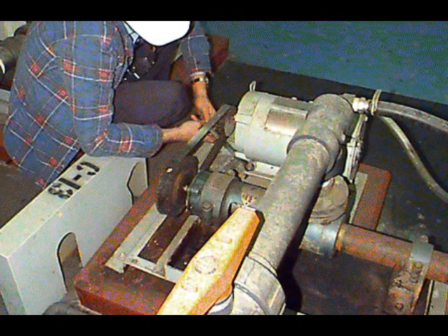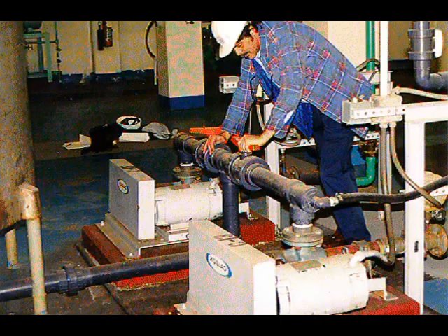First, disconnect the power to the drive. Lock out and tag, then disconnect couplings or loosen the belts. Then grip the drive shaft head with a suitable wrench and turn, being careful not to damage the shaft. Problem: there is no flow. Probable cause: there is an obstruction in the suction line. Make sure all of the valves are open.